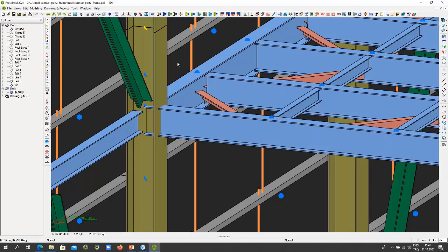And another thing which it does, which is very different from Auto Connect type solutions, is that sometimes in steel structures, you need to shift elements slightly to the left or right, and this is allowed as long as the shifts are minor, say 5 centimeters, 10 centimeters. The results don't really impact the original analysis. So it's common practice in steel to allow for minor shifting of typically the braces in most cases. So Intelliconnect will also shift the elements if you allow it to.